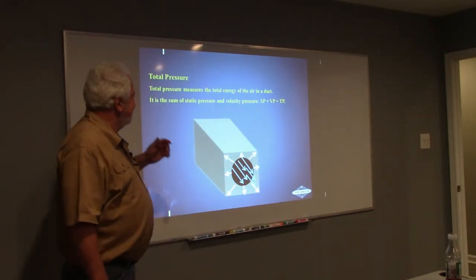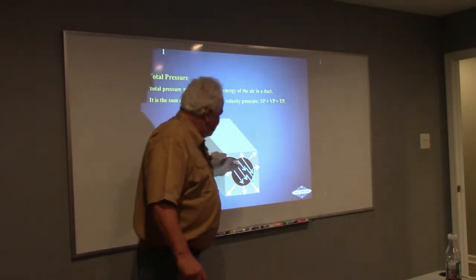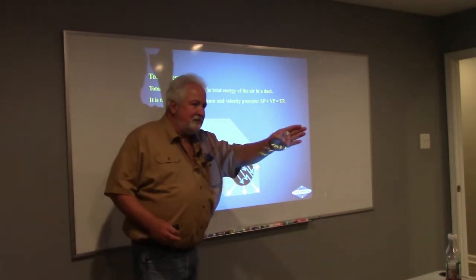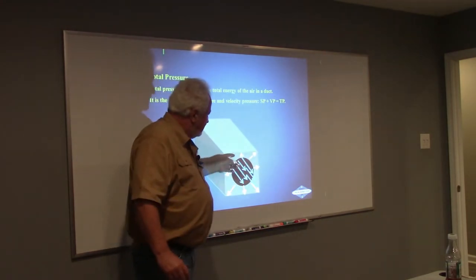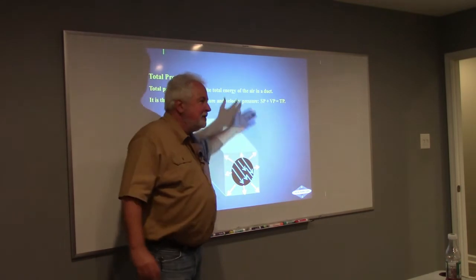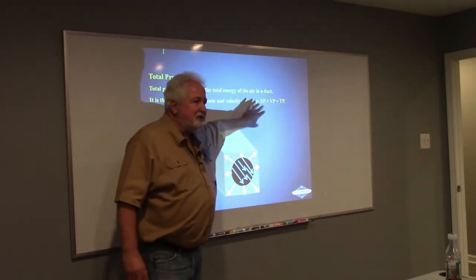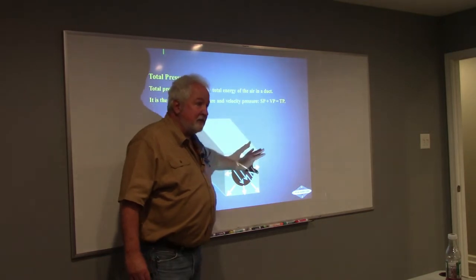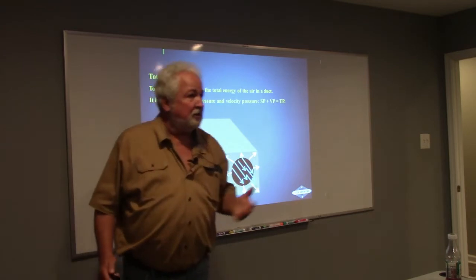All right, so total pressure, guys. Remember we talked about the velocity pressure right down the middle. It likes to be there, it doesn't like to turn. Static pressure is all directions. Total pressure is the combination of static pressure and velocity pressure. Somewhere between nice to know and who gives a damn, because we never measure that. We're primarily focused on the static pressure on our systems.